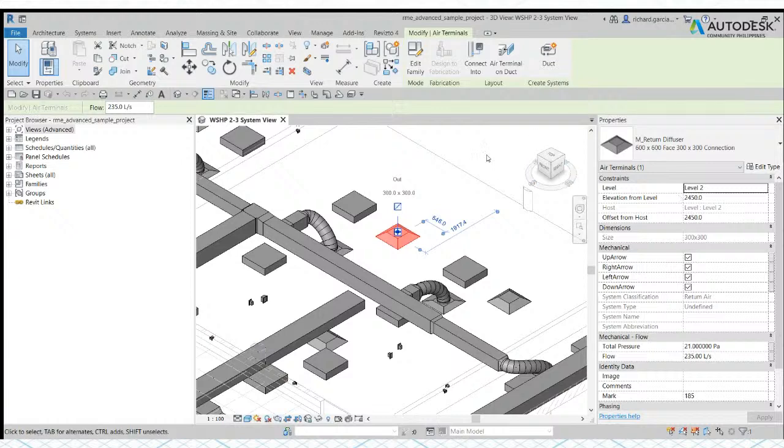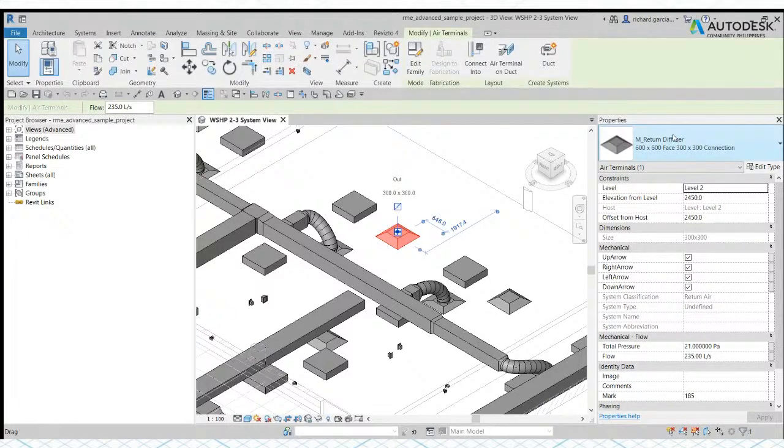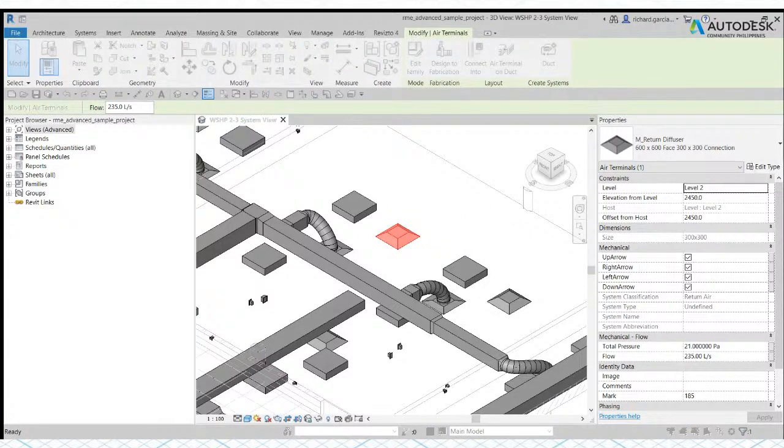Okay, so just a quick recap. So we have the modify to deselect. So this is what? View properties because I didn't select any object. If I click one, so that's now your instance properties. If I click this one here, edit type, you click that one. So this is now your type properties. So basically we have what?